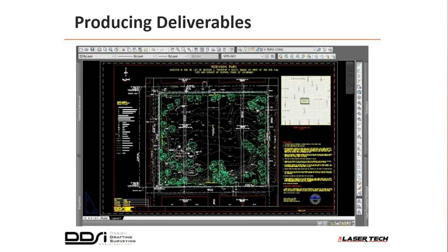We need to create a surface of the 5-acre parcel, so that includes a surface model and a contour. That's derived not only from our drone data, but our traditional surveying methods. That also includes engineering grade elevations and the irrigation heads captured using the laser offsets. By using all the different tools in our toolbox and our routinely implemented laser offset routine, we're able to deliver this project on time and under budget.